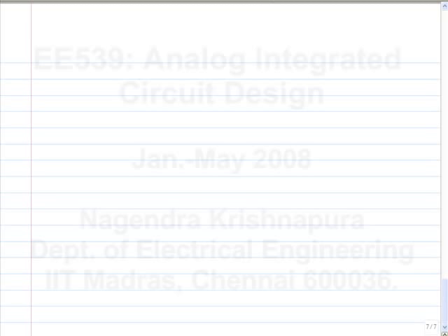Now, the model for the PMOS transistor is the same, except that all voltages and currents are reversed, right? This is an NMOS. So if this is the source, it operates with a positive VDS, positive VGS, okay, and a positive VSB.